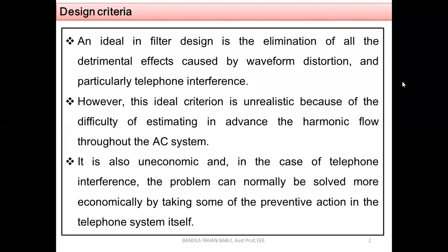Okay, so the purpose of placing the filters here is, there exist two cases, that is at the AC side and at the DC side. We need to filter out the harmonics; in case of DC we call them ripples, and on the AC side we call them harmonics.